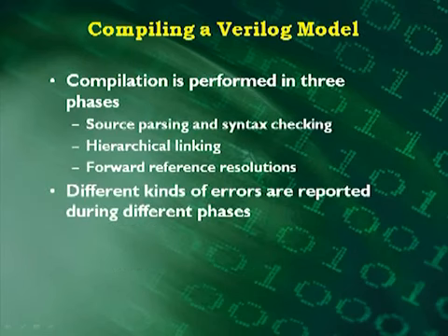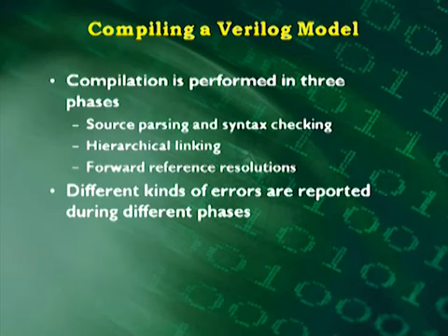Typically, for Verilog, compilation is performed in 3 phases. It does the source parsing and syntax checking, then hierarchical linking, and forward reference resolution. And you'll get different kinds of errors reported during different phases.